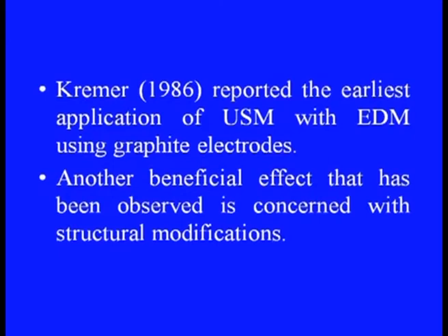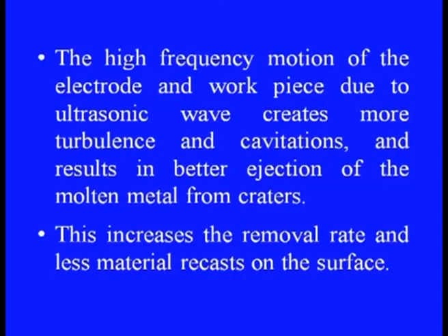Another beneficial effect that has been observed is concerned with the structural modifications because of this hybridization. The high frequency motion of the electrode and the workpiece due to ultrasonic wave creates more turbulence and cavitations, and this results in better ejection of the molten metal from the craters.